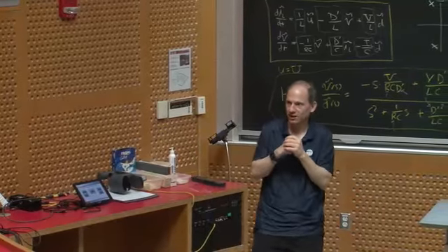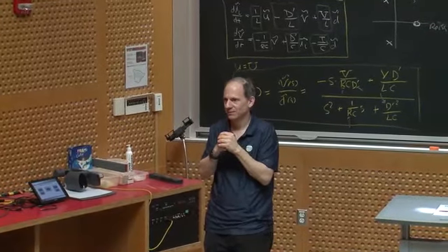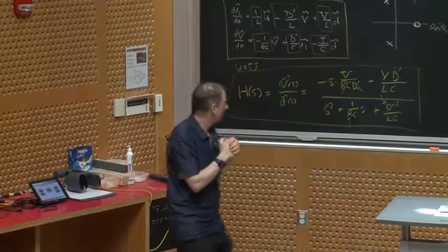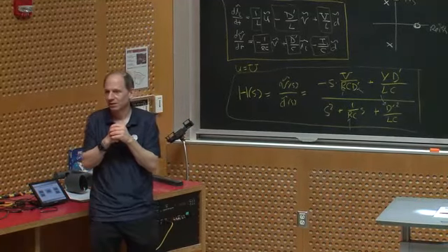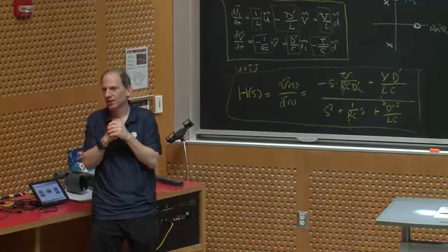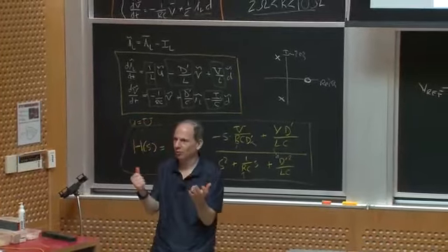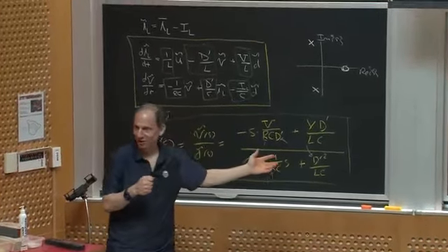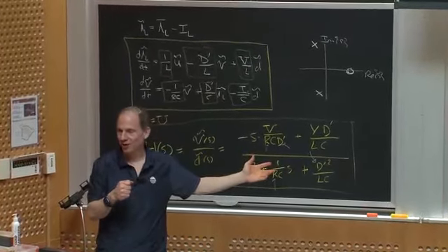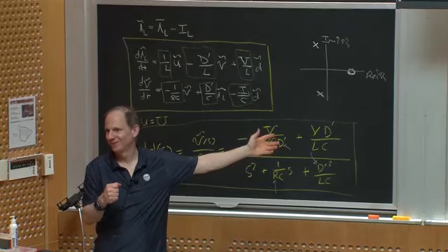Yeah, Jack? The phase margin for the transfer function from B to B. Yeah, that's true. That's why you showed us the load step, that phase margin is different. That's right. But on the other hand, from a small signal point of view, all the pole locations are right. Once I have a linear system, the pole locations are the same for any input, right?